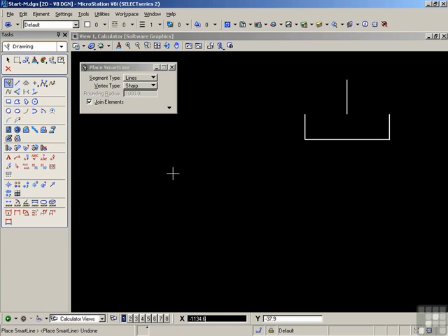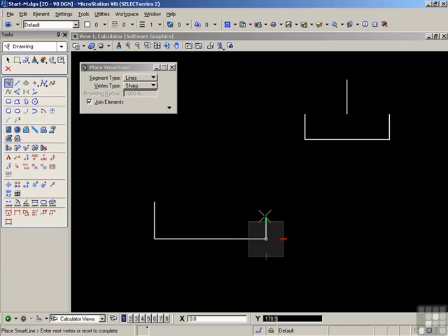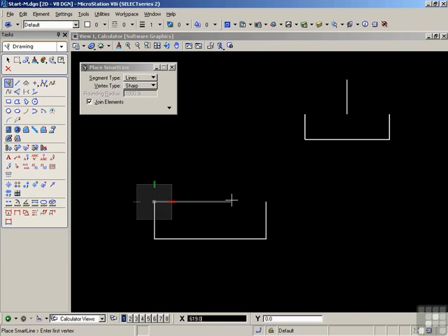Let me show you. Line tool is still running. Let me draw the U-shaped object first. Enter, snap, and draw. Now to find the midpoint, I need a calculation because I have no specific dimensions here. So, line tool still running. Find this snap point, locate the compass at that point, press the O key, drag across to the opposing snap point, and now I need to divide that dynamic line by 2.